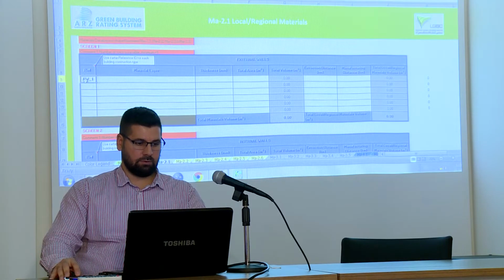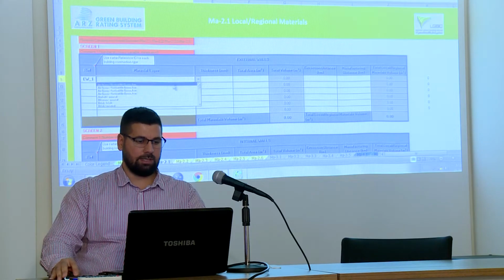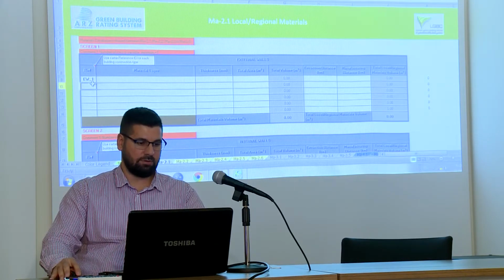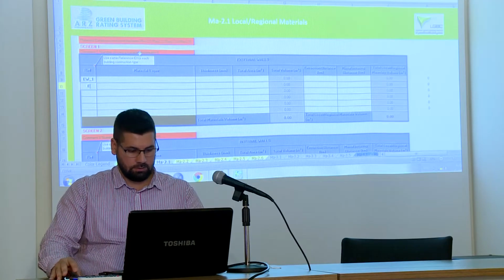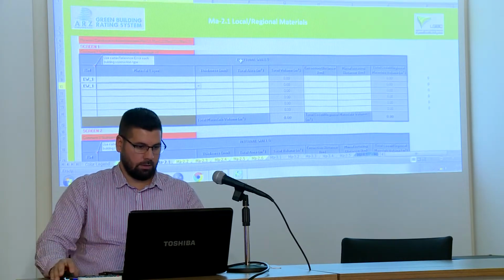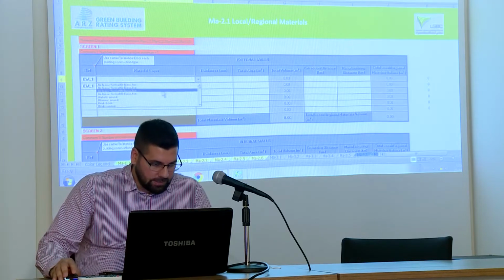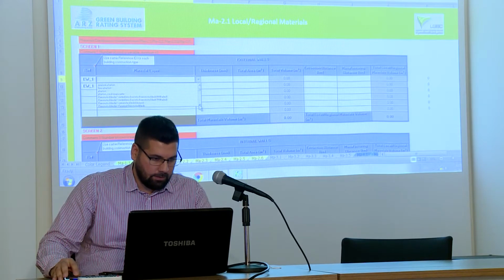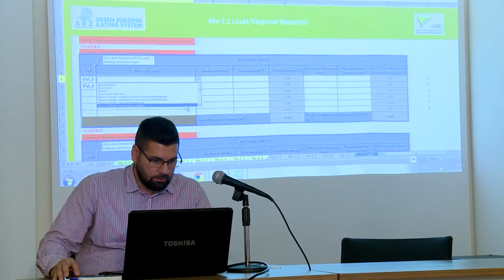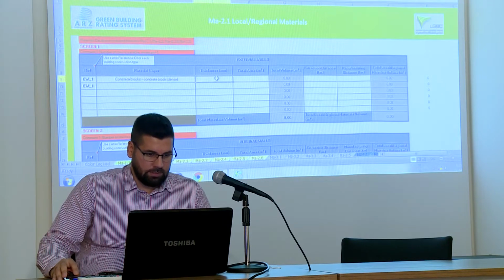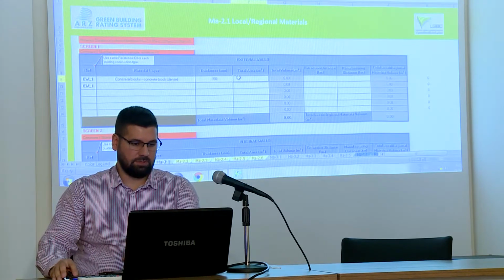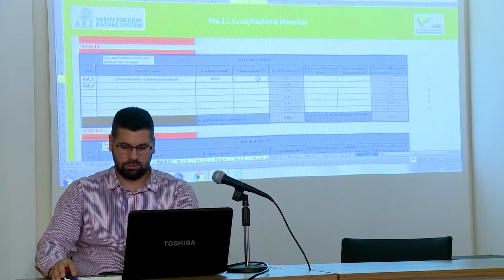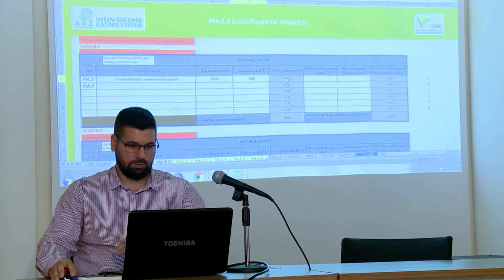Let's take an example, the external walls. First, we enter the reference for the wall. Here, we are entering material layers. So if a wall is constructed of 3 layers or more, we have to input the same reference number here at the beginning. So EW_1. Material layer, we can say it's an external wall, so most probably it should have concrete blocks. Let's say this one. The thickness, 150 millimeters, 15 centimeters. The total area of the whole external walls, 500 square meters.